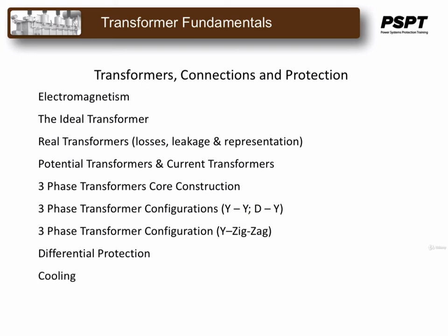We will then look at cooling, and we will look at a mechanical protection device called the Buchholz relay, which is made to monitor the gas accumulation in a transformer. And finally, we will look at oil analysis in a transformer, which is fundamentally important to maintaining power transformers.